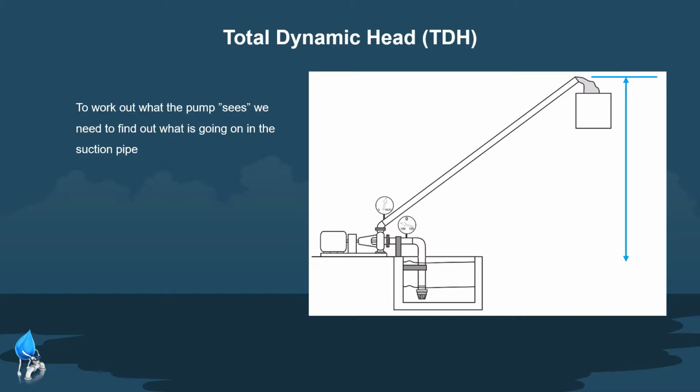It won't change with time or due to levels, as the pipe discharges into the top of a reservoir or tank, and it is not affected by the conditions within the tank. We do, however, notice that the suction sump level can change depending on whether the sump is empty or full, and this can greatly increase the amount of work that the pump needs to perform in order to lift the volume of liquid, and this is dependent on the total dynamic head that the pump experiences.